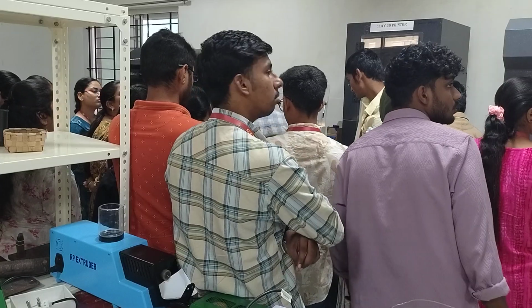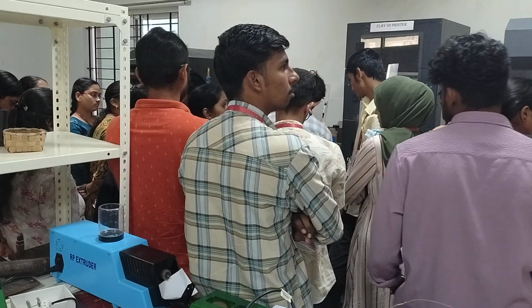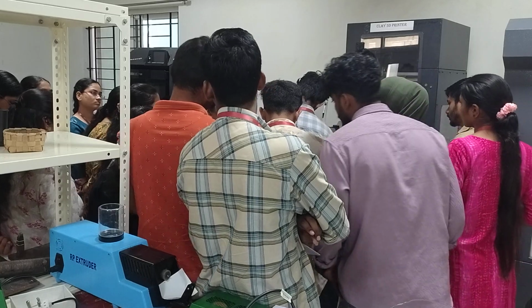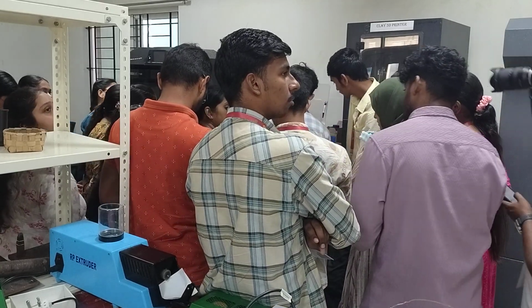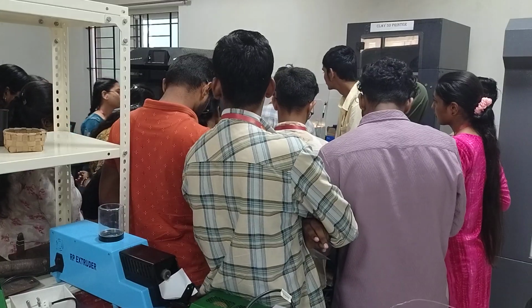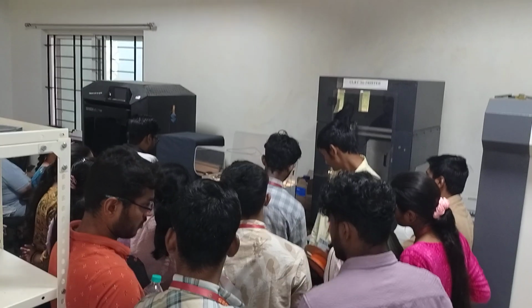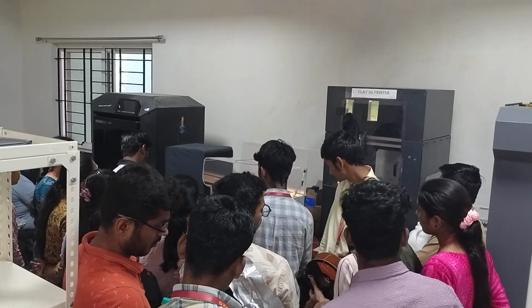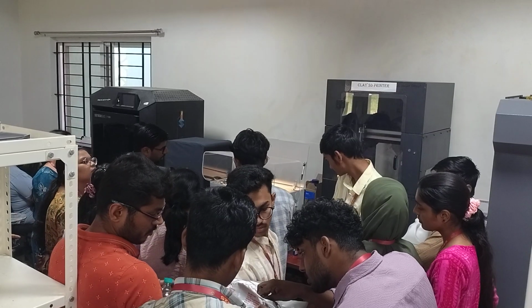Now it's telling put the plastic into the filament feed tube. Until the extruder is loaded, wait for the plastic to feed through the tube. When the plastic starts coming out of the nozzle, press stop. So still it is not coming, it is trying to push, and it will try to come out of the nozzle. The reason why it is not coming is it is not matching with the gear which is used for pushing the extruder. So I'll give a small push from here.